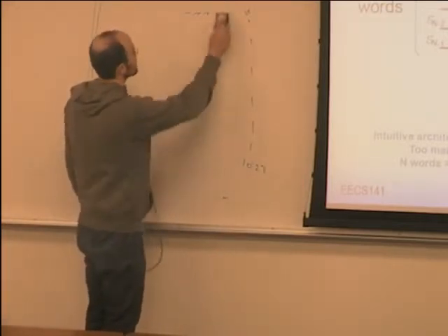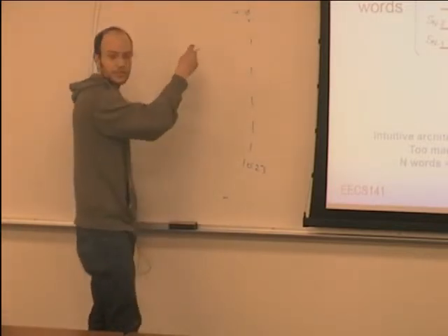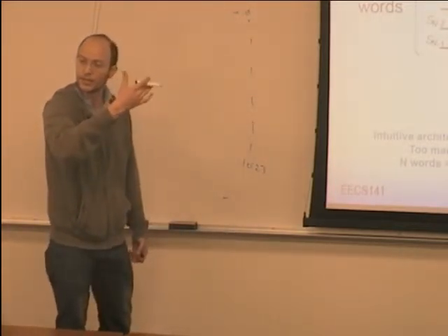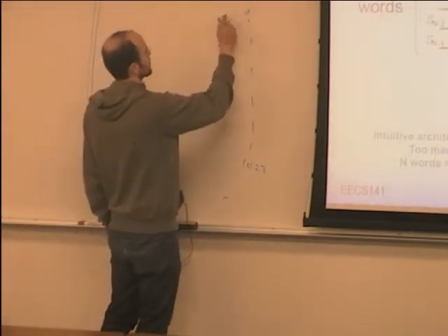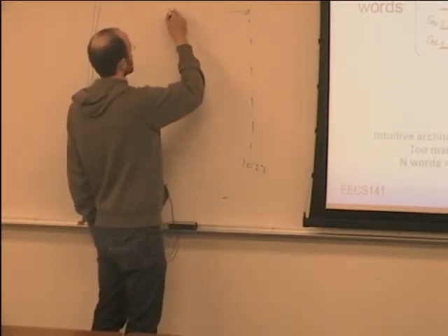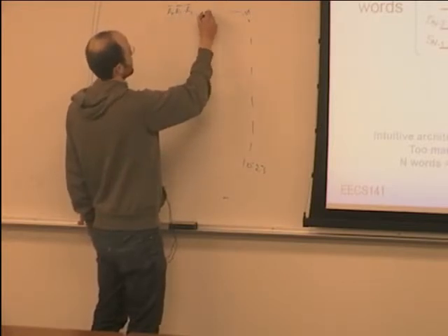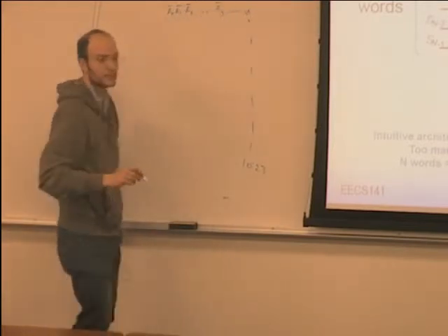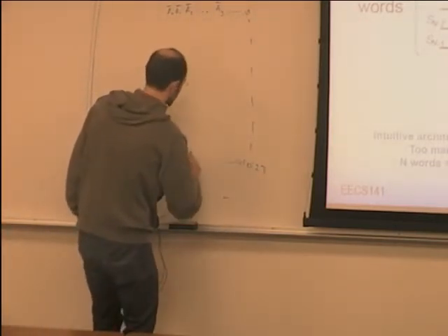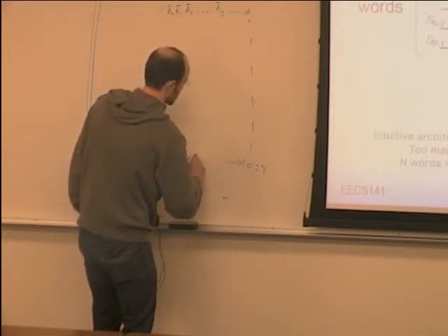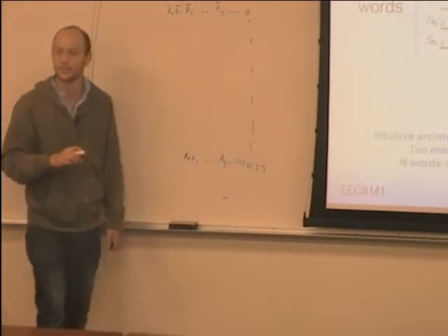So for this guy, I can say that I want this wire to be high when all the inputs are 0. So whatever is connected here is given by A0 bar, A1 bar, A2 bar, and so on, up to A9 bar. Now, for this guy, what I'm going to connect it to is A0, A1, and so on, up to A9. So these are all negated, these are all non-negated.